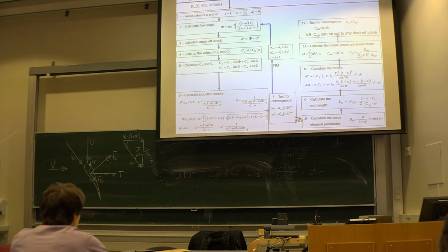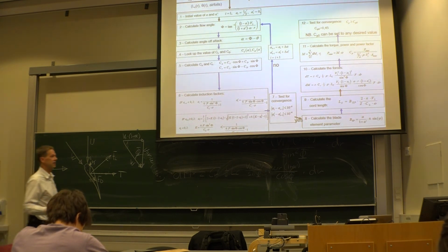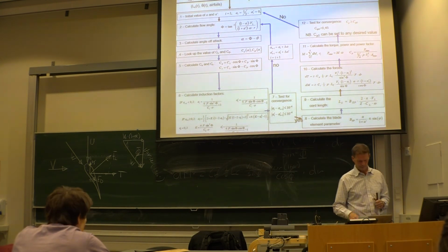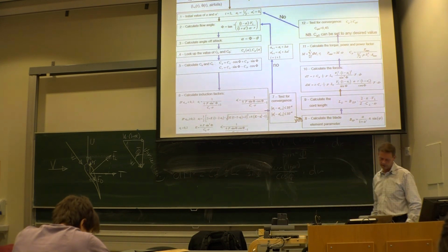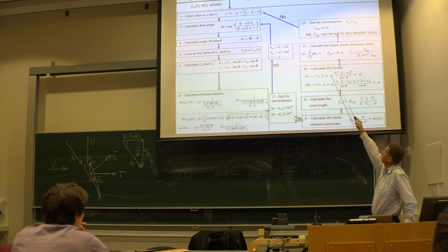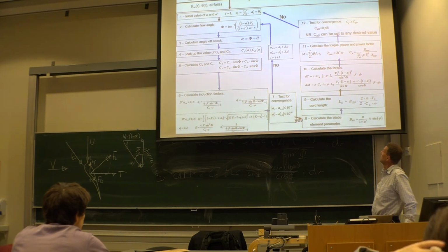So that comes now, because at number 12 there, I want to find out if my efficiency is good enough. And most likely, the twist angle is way off. It's not going to be good. So we have to go back and then twist it or change the length of the blade. So from 12 and back again, you need to change the geometry of the turbine.